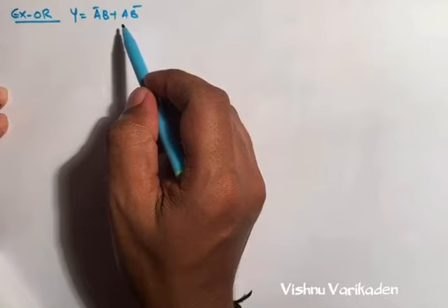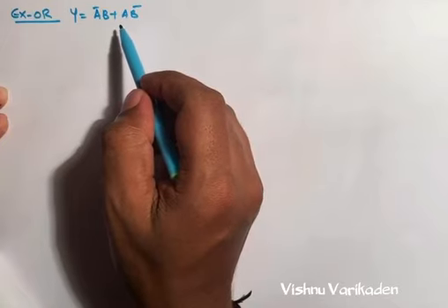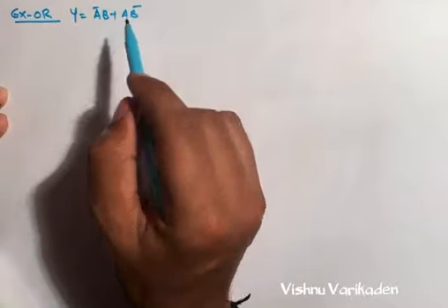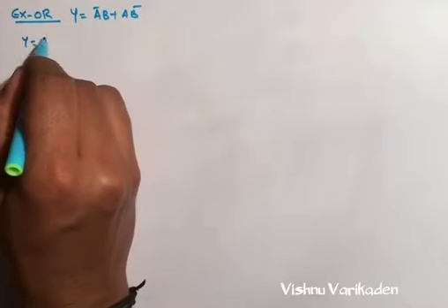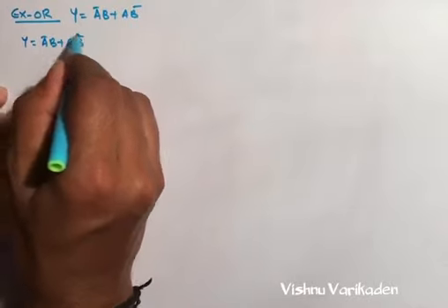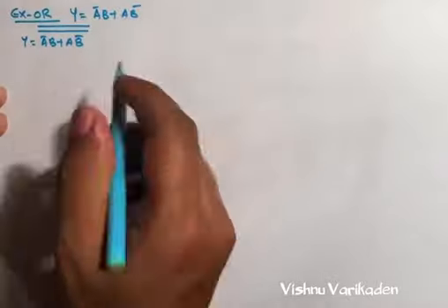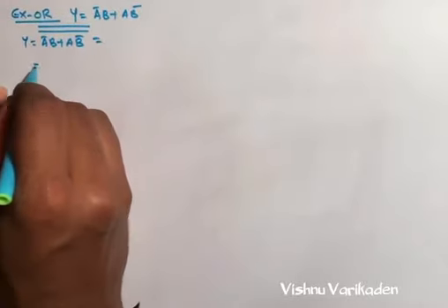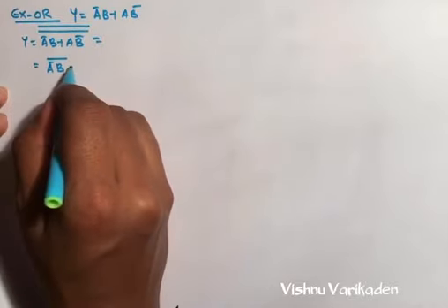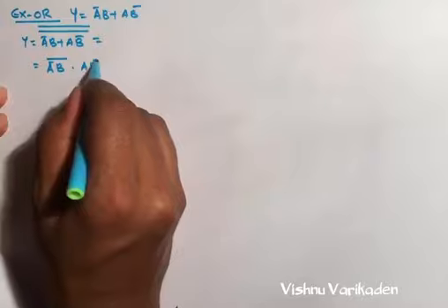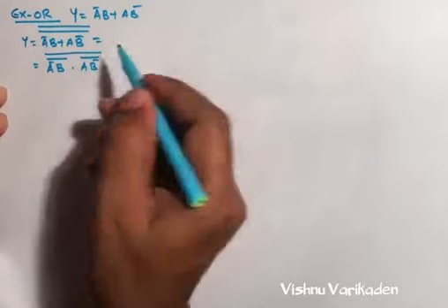So if you are implementing any circuits in this, we can use the inverter at the output stage for normal output. So in this case there is no bar output, so we can apply De Morgan's theorem. So double bar is here, so we can write this as (A bar B whole bar dot A B bar whole bar) whole bar.